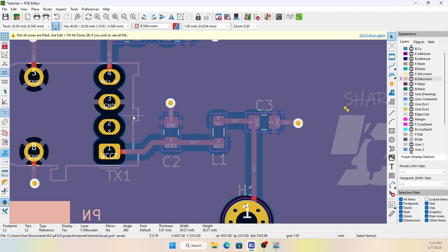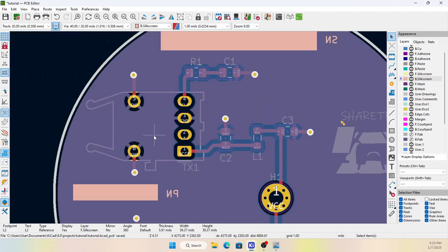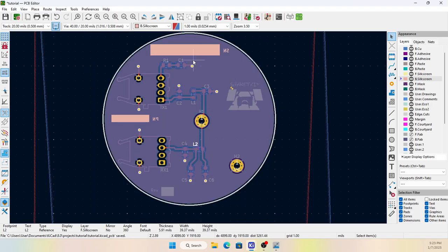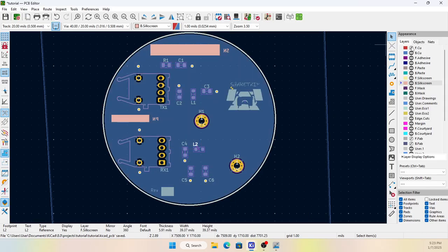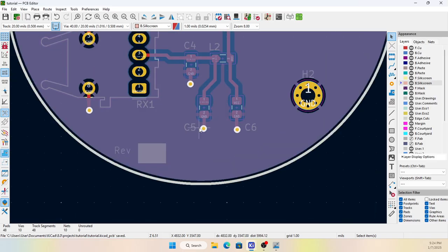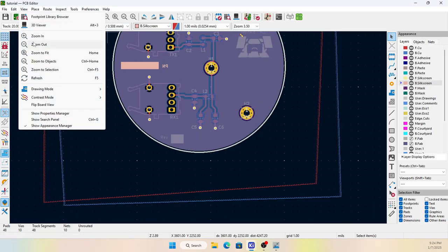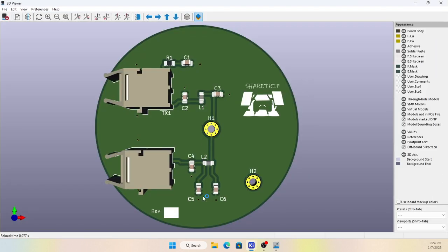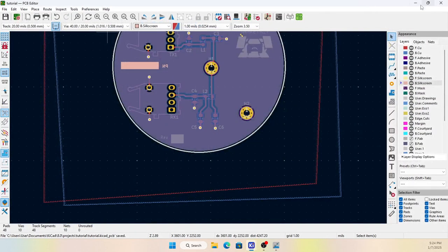And then here you fill out B. I will fill up. Okay, so you can hide the top, you can hide the bottom, save. Now, because we made those changes, you look at the Gerbers, right? We just made those changes. So go to view, 3D view, it looks now like this. But the Gerbers that we made, if we go to Gerber viewer, it's not gonna look like that.